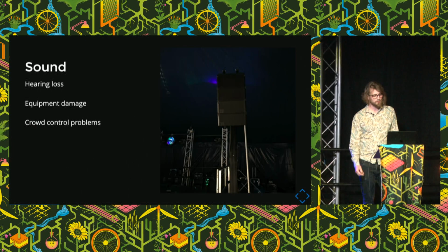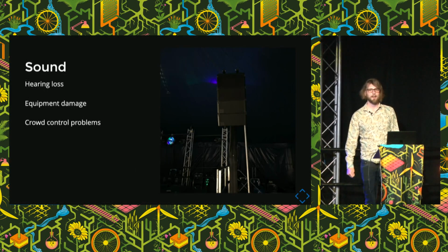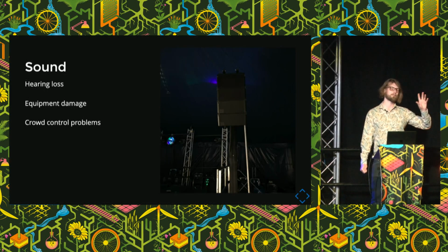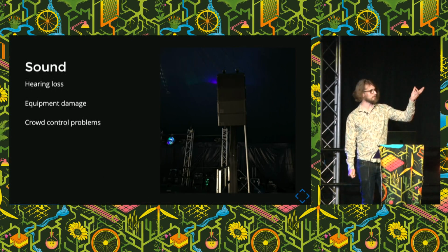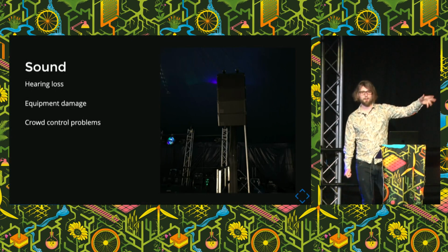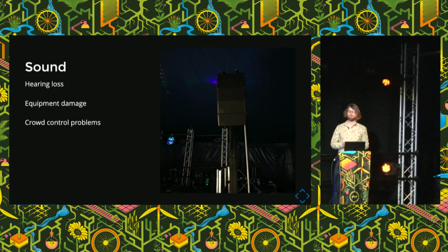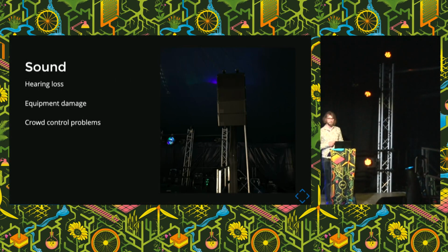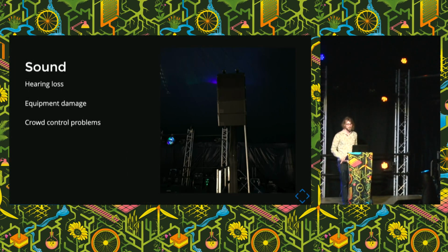The second thing is slightly less obvious, equipment damage. So, you know, loudspeakers, they have transducers in them. These transducers can be damaged in multiple ways. You can overheat the speaker coil by playing square waves through it, and it will in a relatively short period of time overheat and stop being as magnetic, which will stop it being as effective as a loudspeaker.